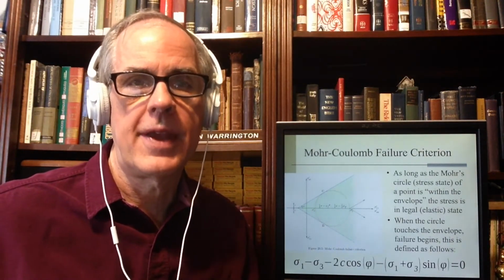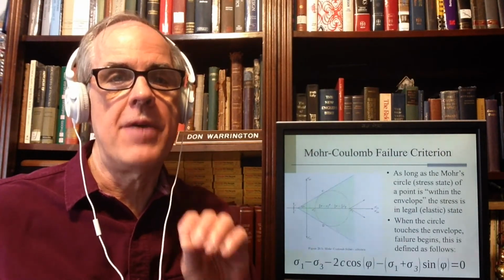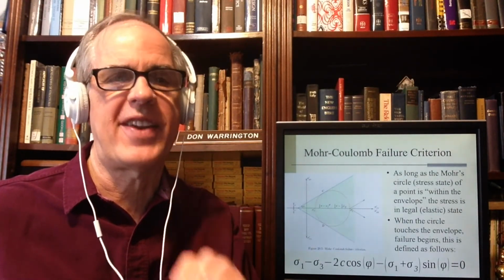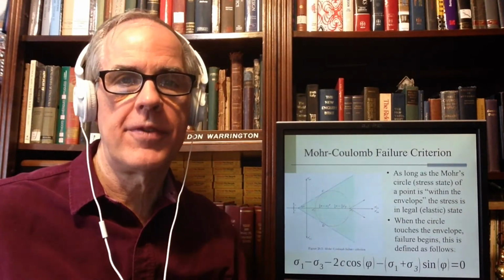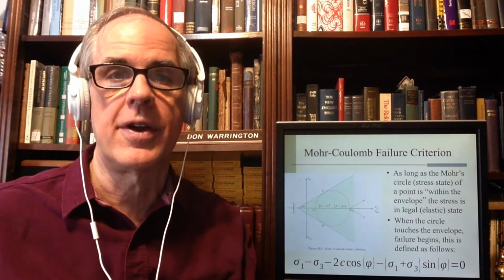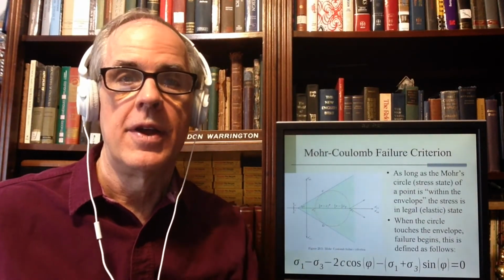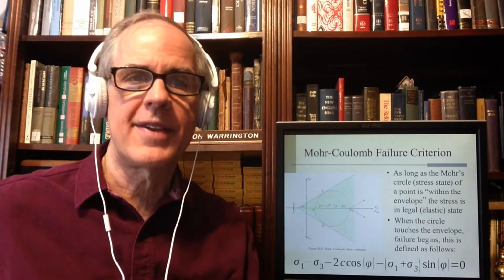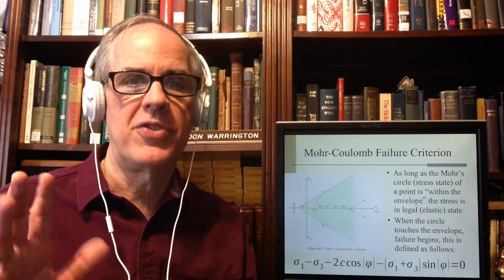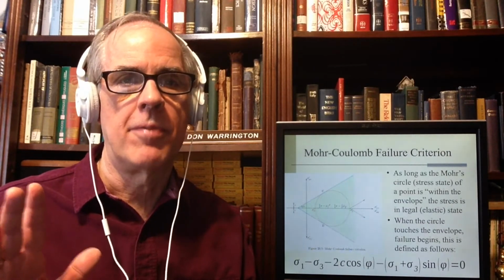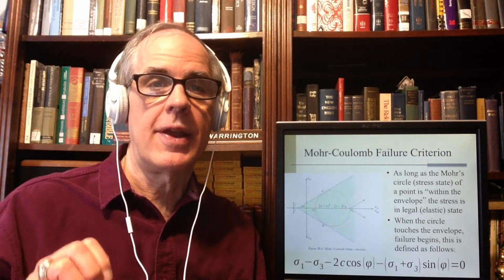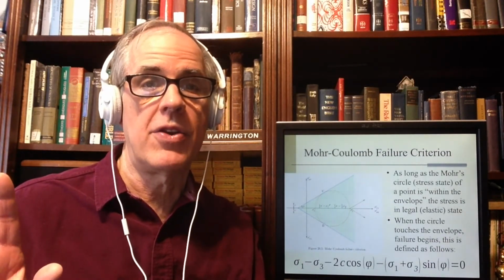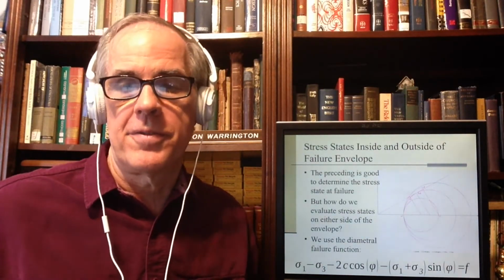And traditionally in solid mechanics, we emphasize that point. We fixate on it, really. That's how we determine if a stress state is subject to failure or not. If it hits that point, it's failed. The question is, that's kind of a hero or zero type of approach to it. It doesn't really help us. And when we get into finite element analysis, we need to know a lot more than that. So what we do is we develop a little thing called the failure function.